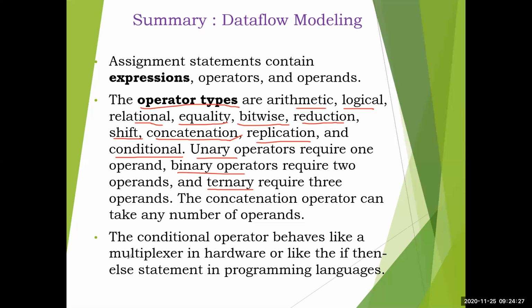Then we saw the conditional operator, which behaves like a multiplexer in hardware, or like if then else in programming languages. It is a behavioral statement that acts as an if else statement. We saw examples, including a 4:1 multiplexer design using 3:1 muxes, where we used nested conditional operators also.